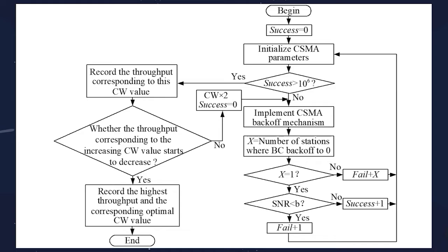But due to the possible poor channel conditions, the transmitted packet is affected by log-normal fading and noise. For X equal to 1 in each cycle, we generate a random number that obeys log-normal fading under a certain variance, and generate the noise according to a binary Gaussian process.